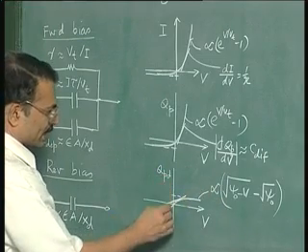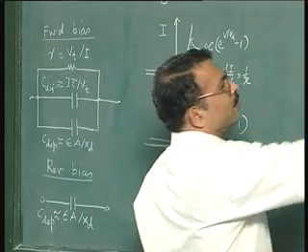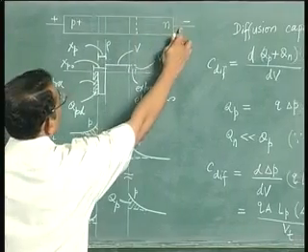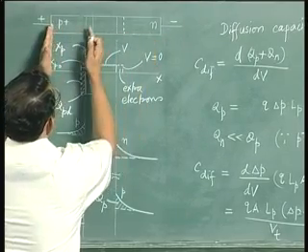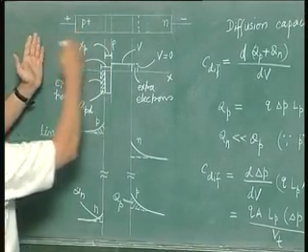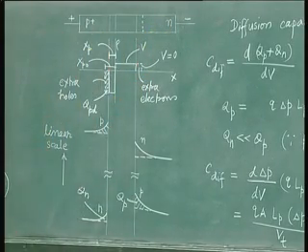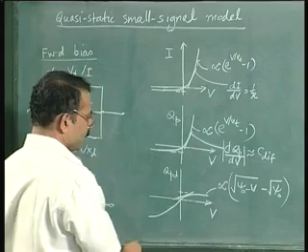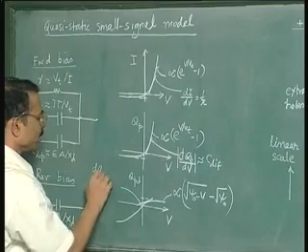You see that QPD is negative for reverse bias because when you apply reverse bias, this is positive with respect to this and then the depletion region expands. So the quasi neutral region shrinks. So you are extracting holes from this side and electrons from the other side. So the extracted holes is what is represented here for reverse bias. So you take the slope of this and then you get the depletion capacitance.